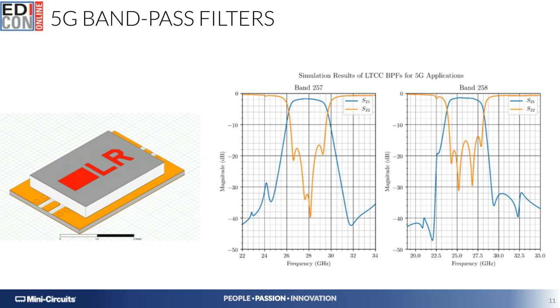Again, we see much lower in-band insertion losses than traditional techniques, traditional materials previously employed by the LTCC industry. Mid-band insertion losses close to 1.3 dB, much deeper in broadband stop band rejections, below 30 dB at frequencies as high as 30, 40, even 45 gigahertz, although these simulation results are limited.